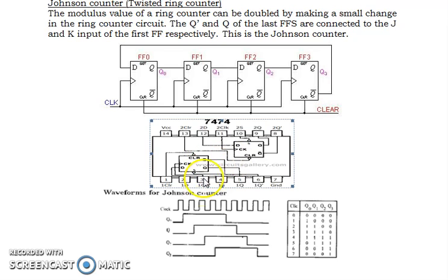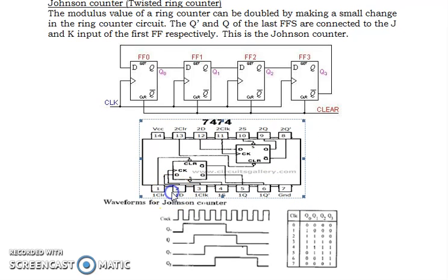Now coming to seeing the output, if you see the pinout diagram here, 1 CLR, 1D, 1 clock, 1 S, 1 Q, 1 Q bar all belong to the first D flip-flop. Then 2 CLR, 2D, 2 clock, 2 S, 2 Q, 2 Q bar all belong to the second D flip-flop. So make sure when you do the connection, you connect it appropriately. Then preset and clear, here it is clear and set, as given in the pinout diagram. Both should be high.